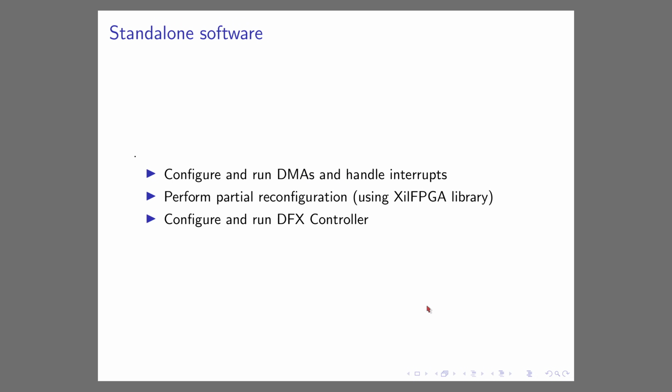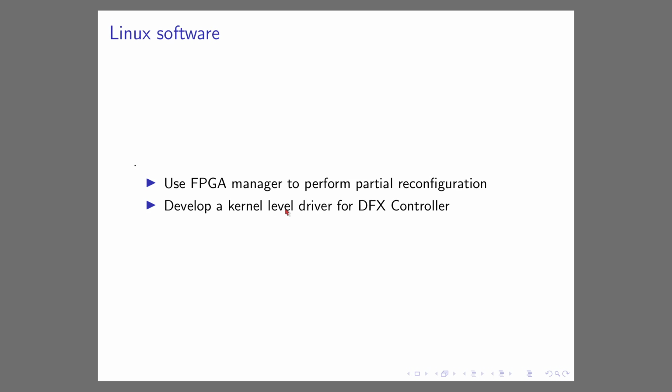So we have the standalone software, which configures and runs the DMAs, performs partial reconfiguration using the ZYNQ PCAP, and configures and runs the DFX controller. And then finally, we have the Linux software, which uses FPGA manager to perform partial reconfiguration. And then also, at the end, we develop a kernel level driver for the DFX controller.